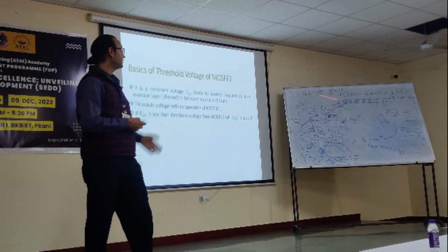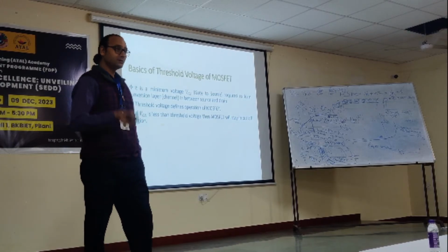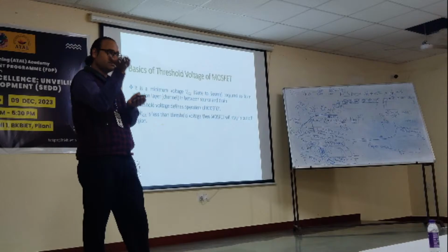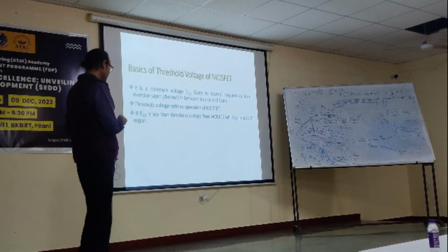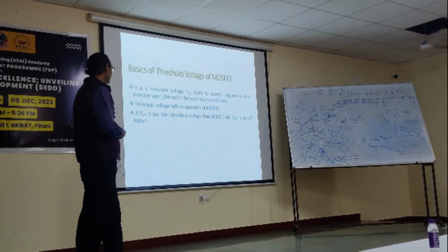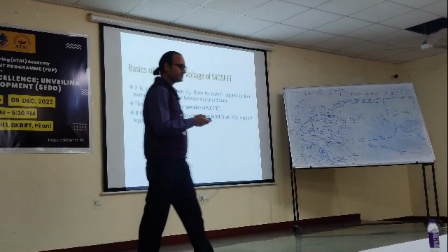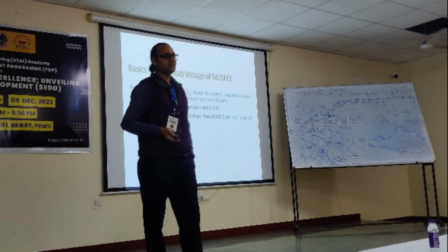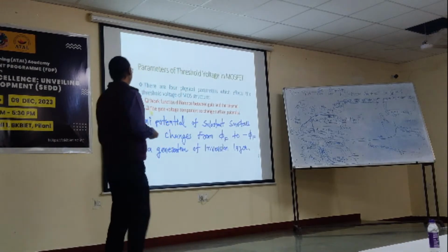We talk only about threshold voltage. On means more than threshold voltage. What about off? Off is also not abrupt, no? Off is not abrupt. There are some leakages. So the last statement is not absolutely right. When VGS is less than threshold voltage, current still flows. We call that leakage current, unwanted current.